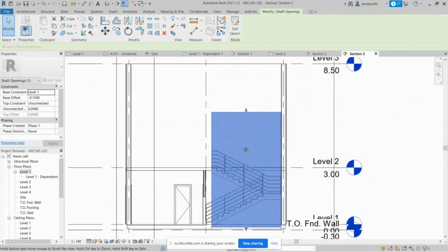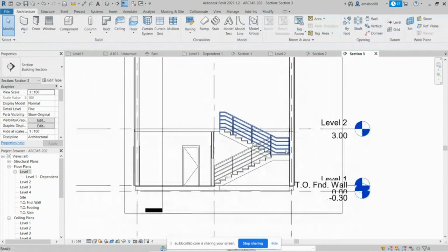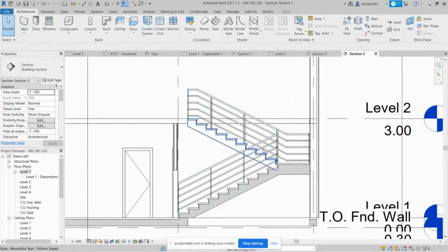If you want to extend it, when you get to the level of the roof, don't expand it, because if you expand it, it will make an opening, and no matter what you draw, it's not going to show. So you have to stop it right below the annex entrance, or the stairs of that. So this is now cleaning up the void for the stair, and they call it the stair room, or the stair void, in order to accommodate our stairs in it like this.